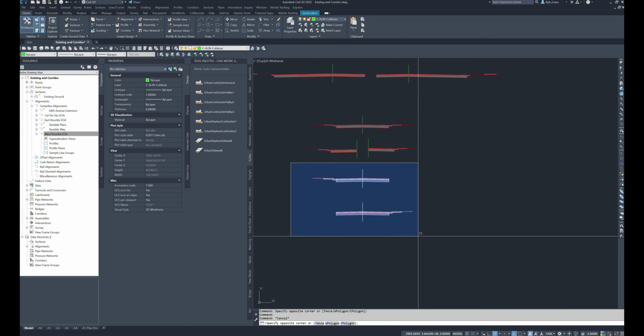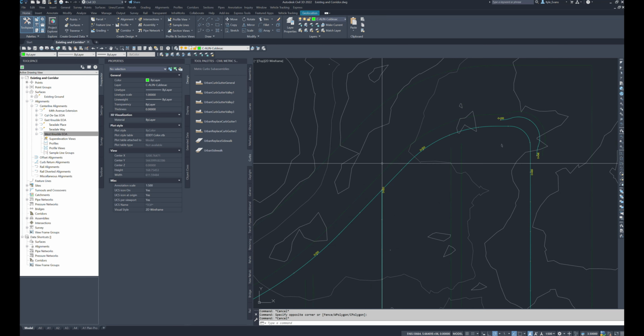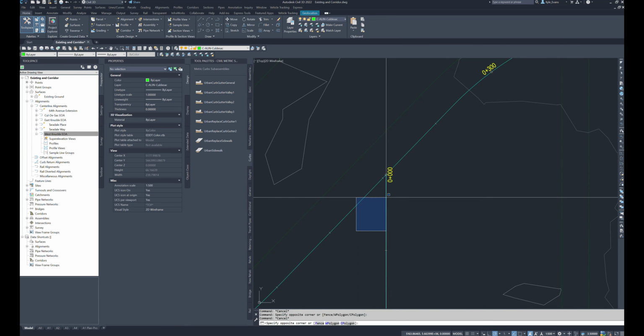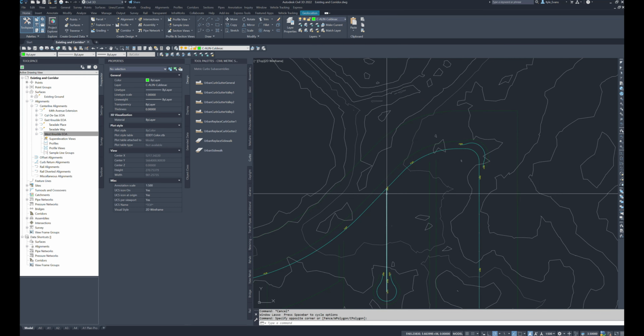These two are, again, for if we potentially go through any intersections. So we have an intersection here. We will need the driving lane on the right, but we need all the other bits on the left. And we're going to have to apply these and change them up in our corridor as we go through it, but we will get to that in the corridor video.